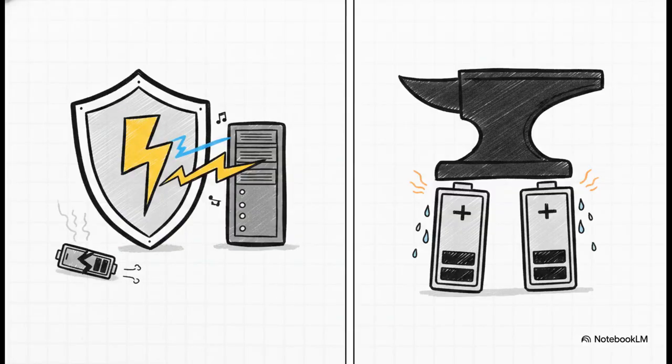So what's the ultimate takeaway for this setup? Well, the major advantage is incredibly high survivability. Even if 1 unit completely gives out, the remaining 2 instantly cover 100% of the load without even breaking a sweat. The flip side, though, is that the baseline stress on the machines is a little bit higher during normal operations, since they're constantly running at that 66.6% capacity mark.